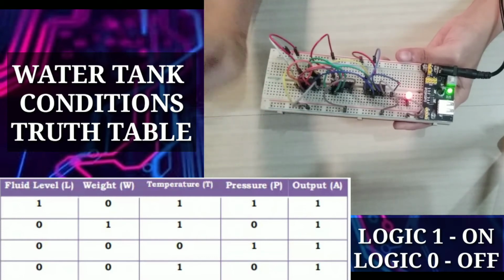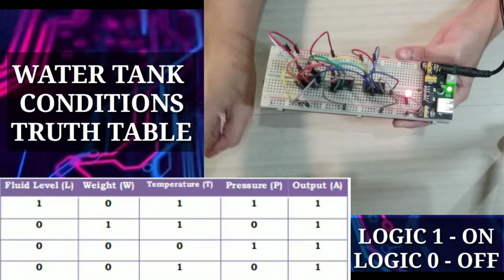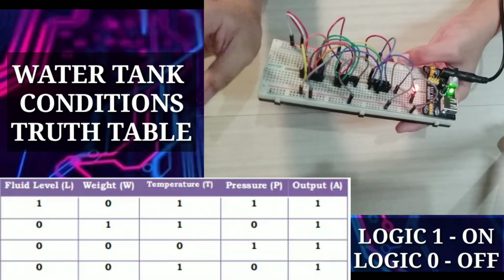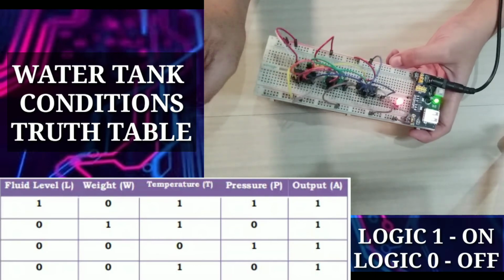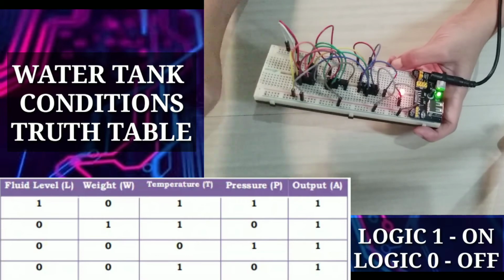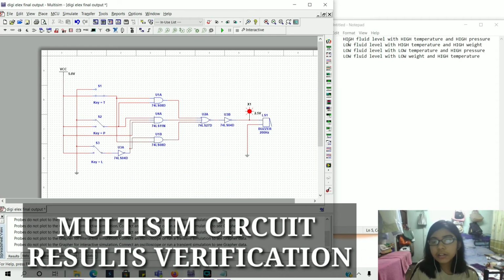Overall, if our fourth condition is satisfied, wherein the fluid level is low, the weight is low, and the temperature is high, our output will be at logic 1, meaning the alarm will turn on. So that's our truth table for the tank conditions. As we see on this side, these are the conditions that we should satisfy. And this is the circuit that we're going to test for the following conditions.